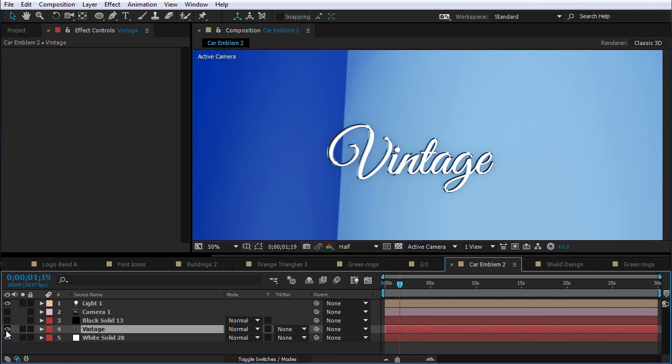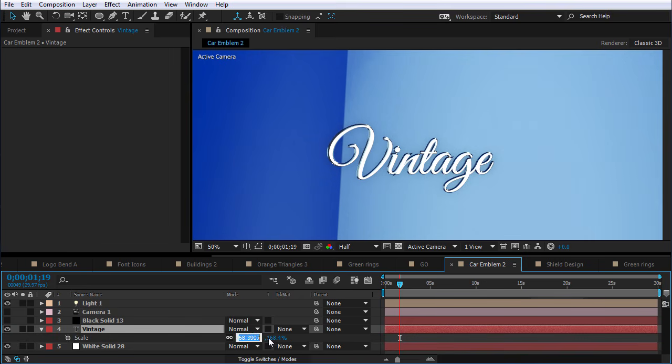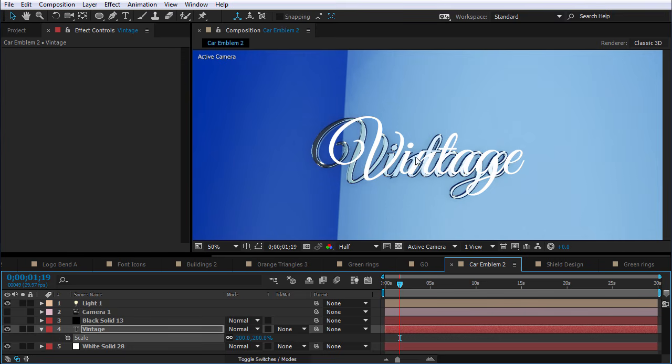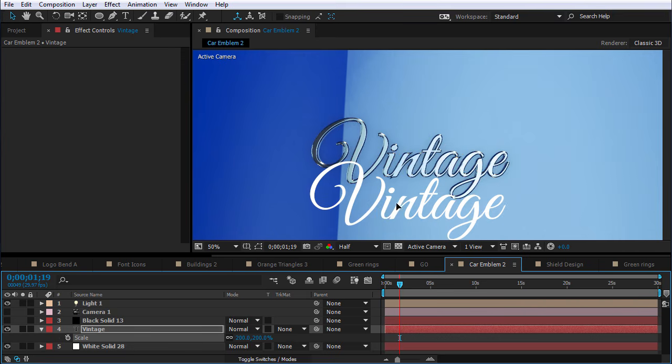And that's because we've added a new feature called Bevel World Scale. So what that will do is automatically keep the size of the text the same as the size of the text that you create. So if I were to take this text here, hit S, scale it up to 200, my 3D text is going to be recreated at the same size.